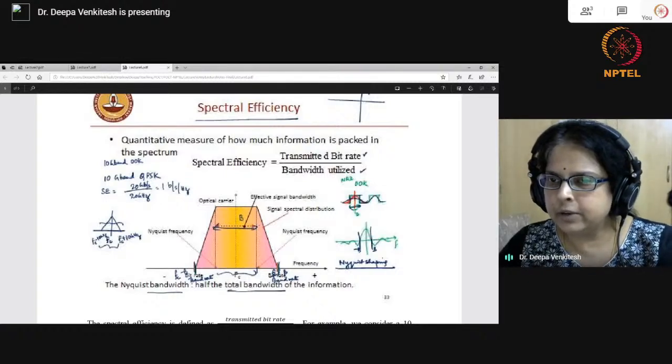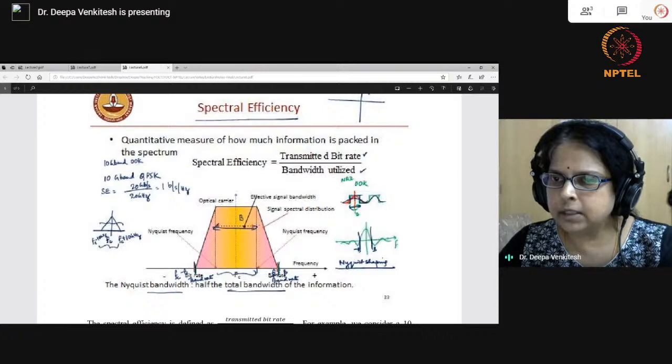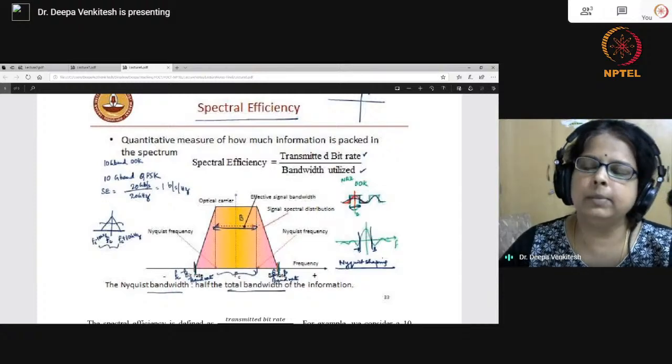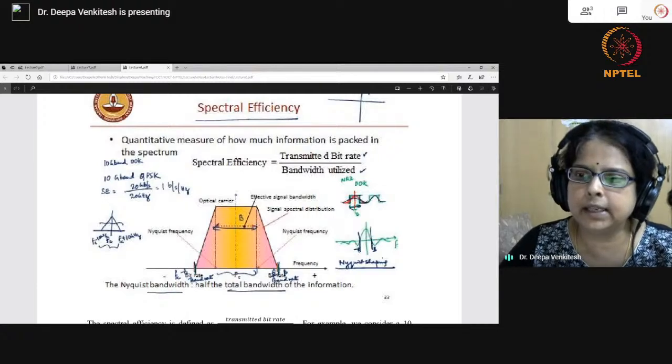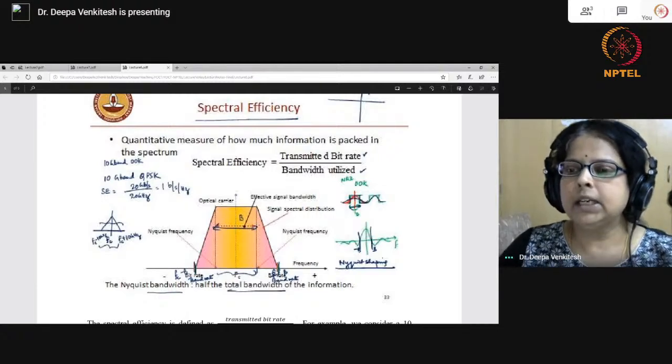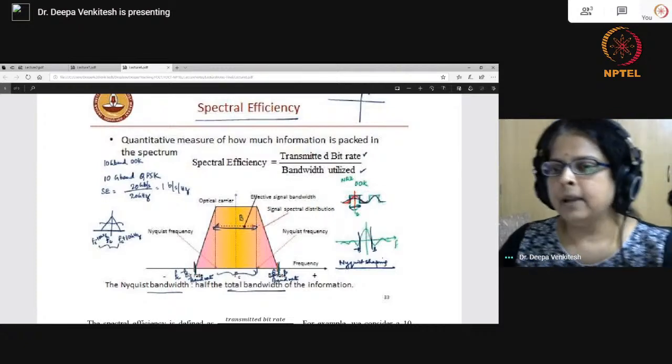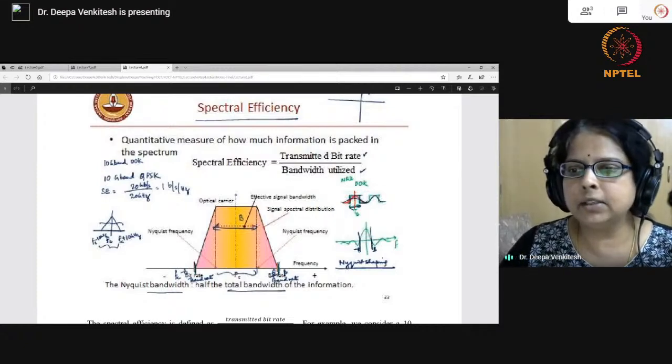There's a question from Anupam. What types of modulation is used in fiber optic communication? Is modulation necessary to transfer signal through fiber? Yes, of course, modulation is necessary to transfer because you're trying to use light as a carrier. So you have to modulate light to transfer your information. What type of modulation is used?